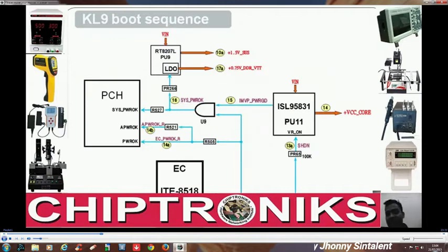And after a delay of 99 millisecond, this IO controller, after getting this H power good, first will generate VRON, and after generating VRON there would be a gap of 99 millisecond, and it will generate EC power OK. This VRON is going to the CPU core regulator, and it will generate the VCC core, and after that this core regulator will generate the CPU core voltages.